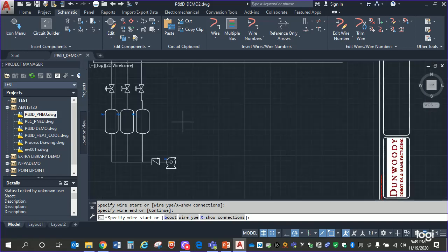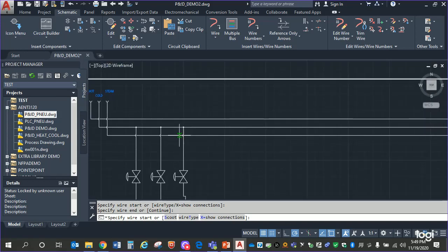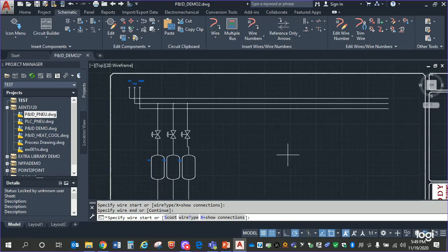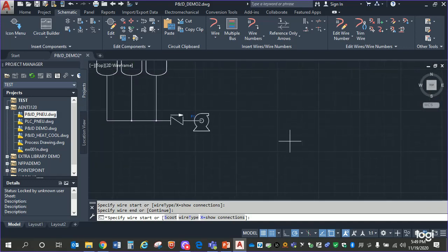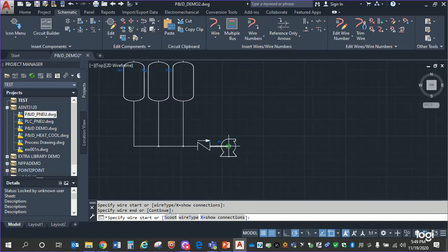I'm going to feed water into this system, and all 3 of these are feeding cold water. The check valve helps guarantee that I'm not going to get flow in the backwards direction. Remember, this is a 2D drawing. I'm not saying that the tanks are up high and the pump is down low. They could be that way, and it probably makes sense to have them that way. But in this case, what the check valve is really doing is once water gets past it, it stays on this side. And if I'm not running the pump, it'll keep a little bit of water sitting there ready to go, too. That's what it'll do.